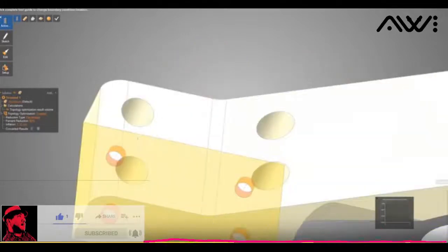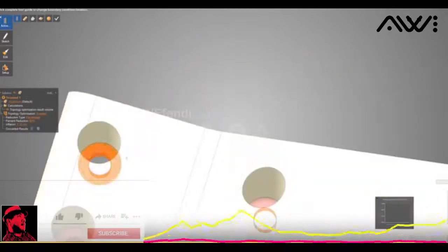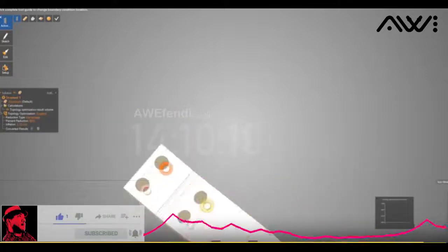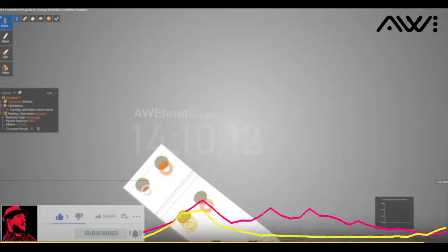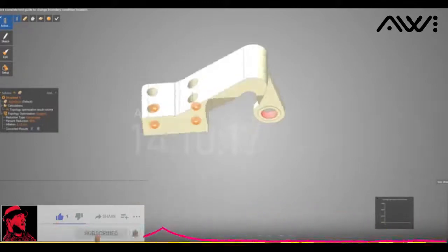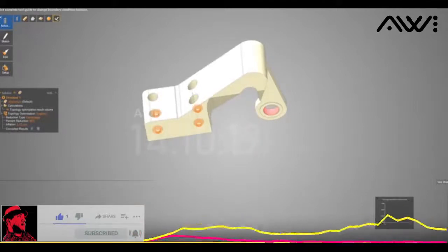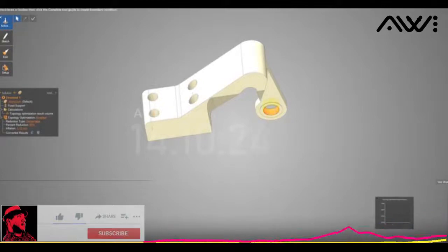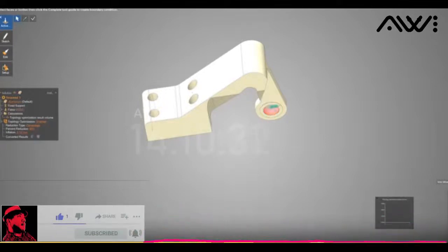But then two, consider these top faces too, right? That's where the bolt's going to have some contact there. So I am just going to these two, my entire process. You see, there's not a lot of selection, right? I have the support. Where's my load going to be now? Just come back under setup, add a force. We'll just put load in that area, and let's just go with up this up a little bit. Let's go with 2,000 newton, whatever for kicks, right?